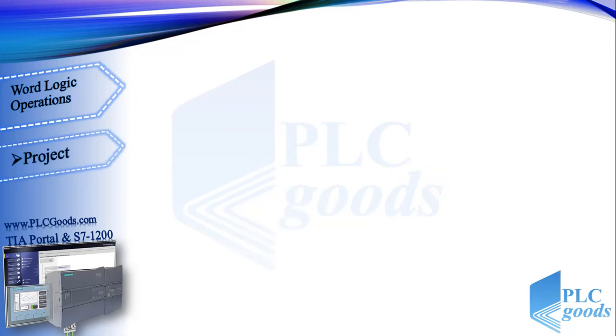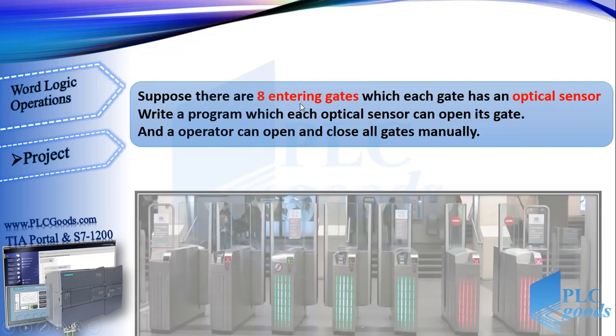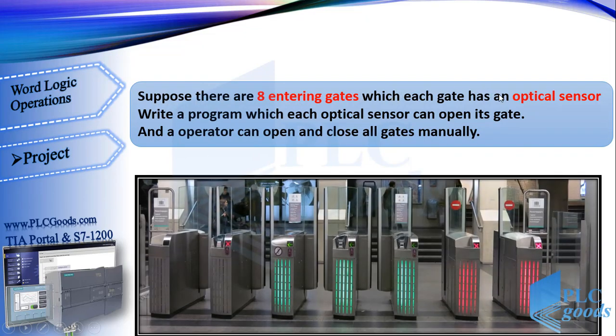Let's do a simple project. Suppose there are 8 entering gates, where each gate has an optical sensor. Write a program in which each optical sensor can open its gate. Also, an operator can open and close all gates manually.